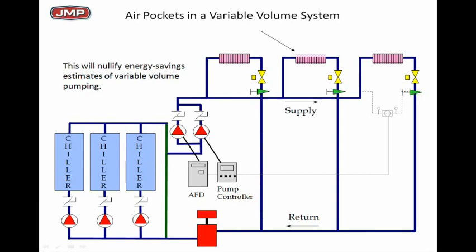Wow. Air pocket's going to cost you money by your pump running faster. Absolutely. You got air in that cooling coil, in that center coil. That means if you got air in a water cooling coil, it's not going to work too well. The heat transfer is not there. So nobody's happy because you're not getting cold air off the coil. You got flow through the coil on the bottom of the coil, but the whole top of your coil is full of air.